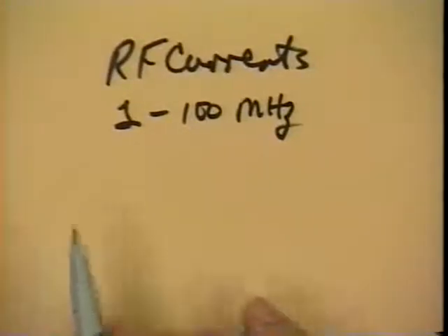Well, we already said most of the ground loop noise is in the kilohertz range. Sometimes it's a few tens of kilohertz, but mostly low kilohertz. So in this situation, if this particular current is multiply tied to ground, then what's going to happen? Those low frequency ground currents are going to get onto the signal wiring. And those low frequency ground currents are going to cause low frequency noise voltages to exist within this RF circuit. But not a problem, we just filter it out.